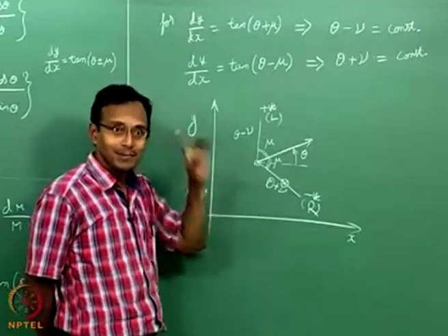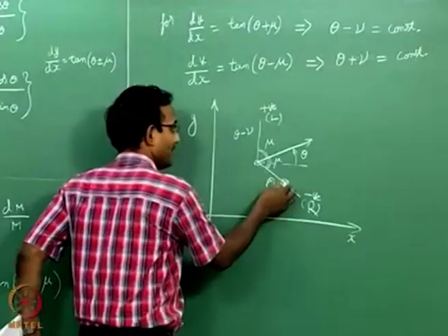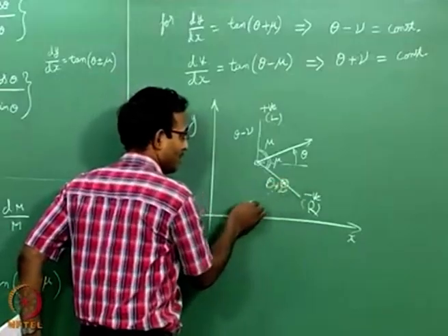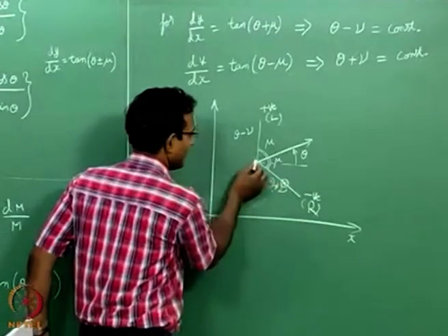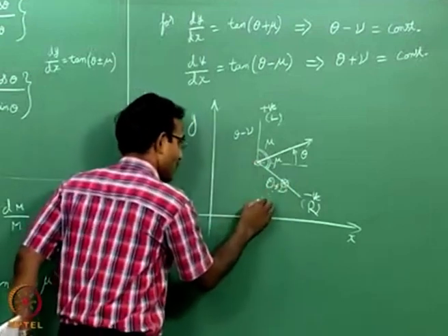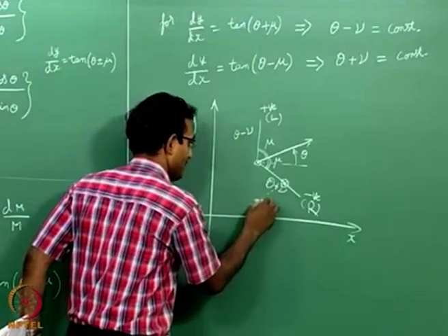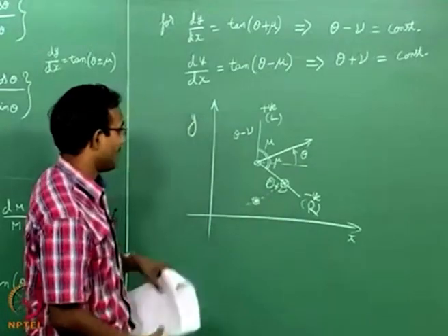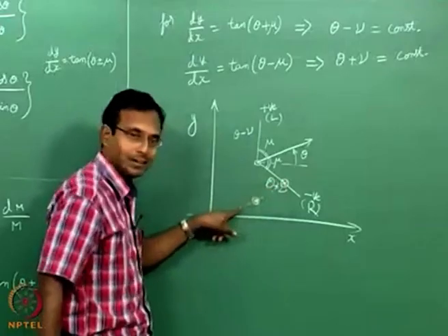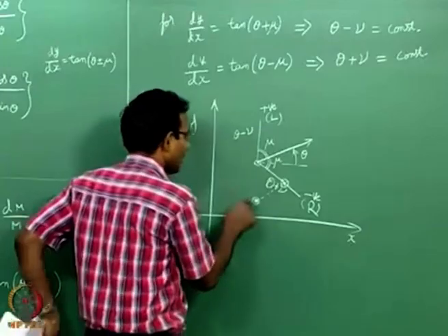Now we go back and think about the zone of dependence, right? This point depends on the upstream cone this direction, right, these two lines. So, I am going to say I need one more point given on this, maybe I will use a star here, one more point given on this line of dependence, where this is going to tell me another theta.